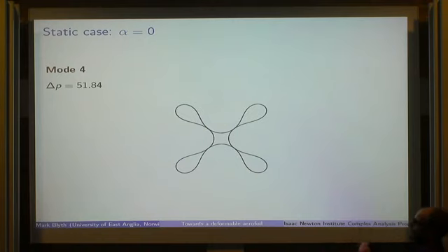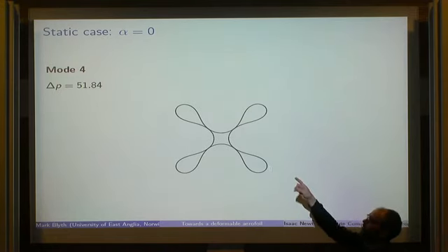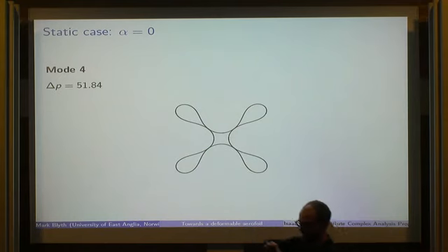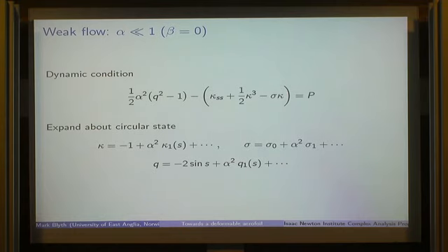And again, you can extend the calculations, and the shapes will self-intersect. The particular feature of Flaherty's paper, incidentally, is that they extended the solution beyond this point, allowing for a line of contact. So you increase delta P, and this point of contact extends out into a line with a local similarity solution describing that step. So you can always do that if you wish.